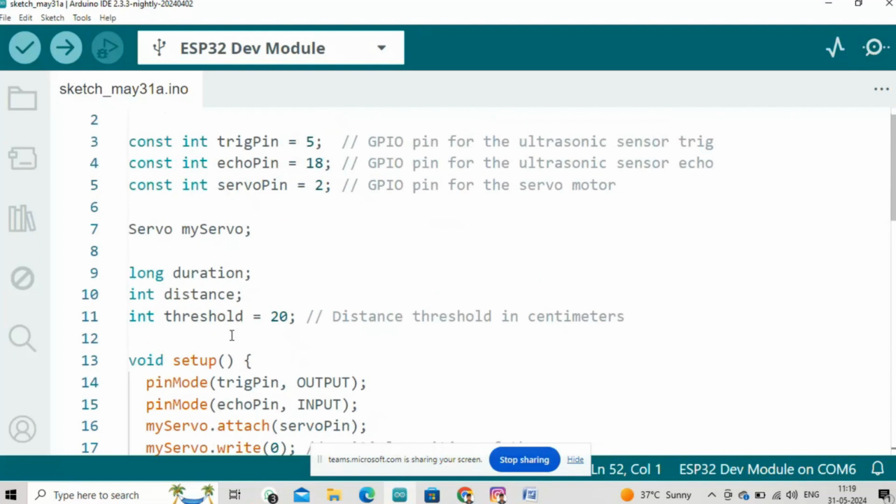Based on the values that we are sending, for example, it is 20 centimeter around that. So the threshold value is 20 centimeter, it will measure the 20 centimeter. Based on the values that we are giving in our code, it takes the values as threshold. So we are giving, for example, 10 milliseconds for the trigger to move and come back.